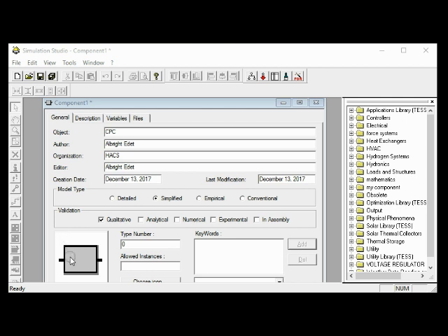Without this image, your proforma or your model cannot be used in Trnsys. So it is very, very important that you must have selected an image different from any other person's image here on Trnsys. Clicking the icon will open the icon editor, which is Microsoft Paint by default, allowing you to select an icon for your model. If this function does not operate correctly, you can reinstall your Trnsys Studio.